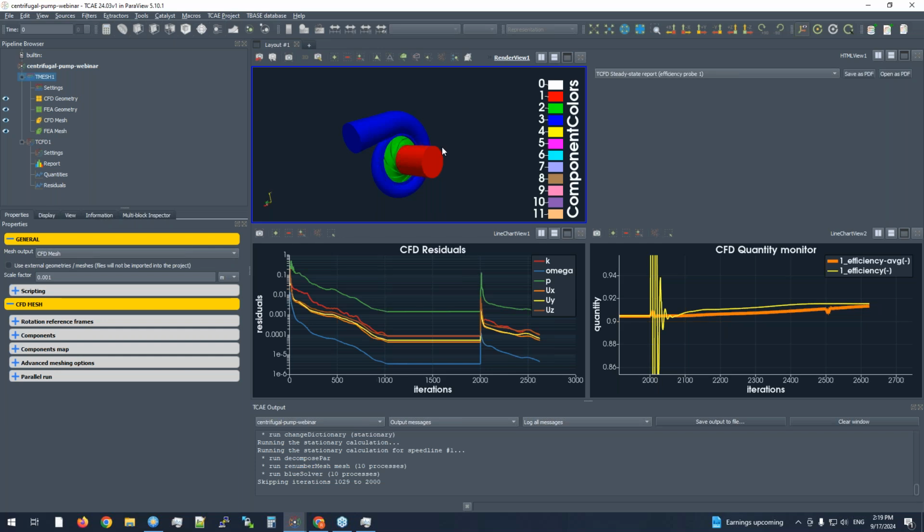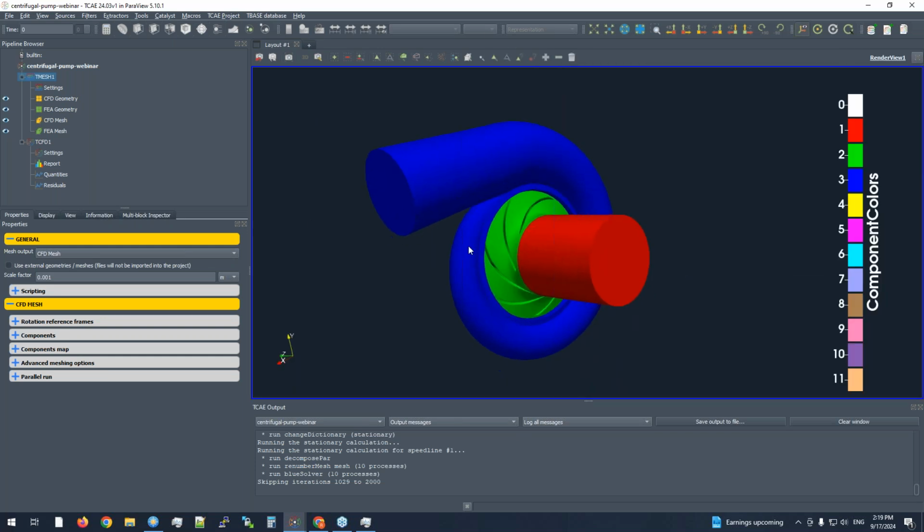So it doesn't work like this. First of all, playing with the meshing. In this render view, we are sticking for a while with the T-mesh module. If you go step by step, typically each module, or each menu which is connected to the given module, works like a wizard. So you can go from the top to the bottom through the overall parameters, and you will not miss any part of the workflow to be set.